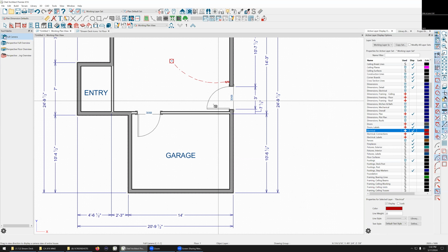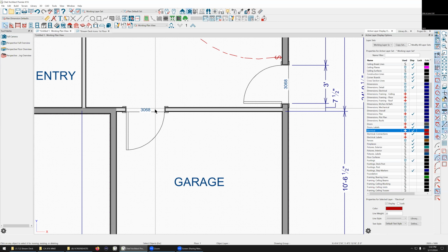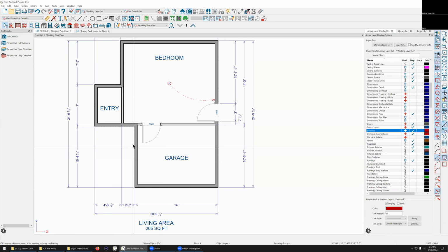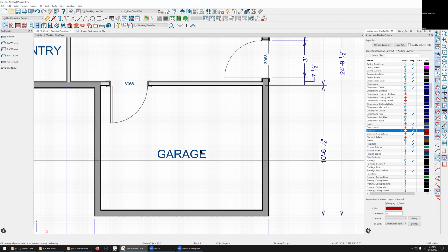It's been that way as long as I know. And so I have to come in and change this manually to slab. It needs to just know, hey, I'm connecting garage to house, slab. Should be always. And the garage should have 5/8 sheetrock. Yep. That's another thing. Another fire rated sheetrock separating the house from the garage.